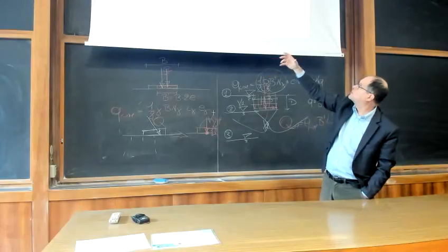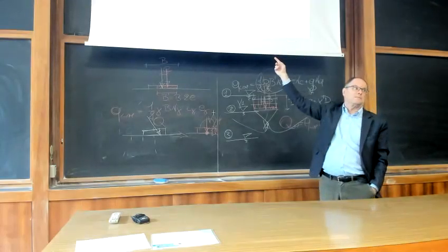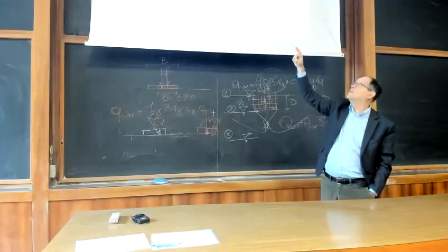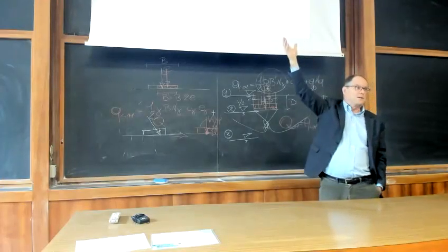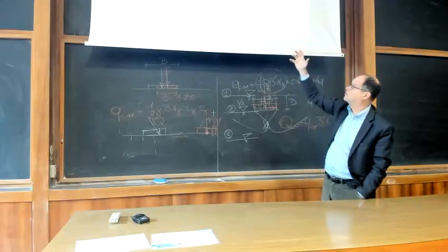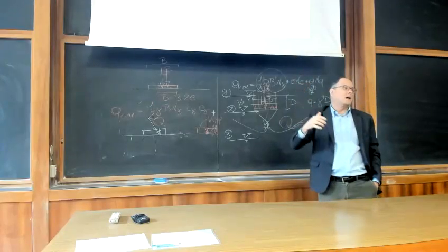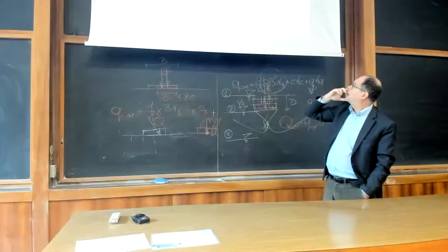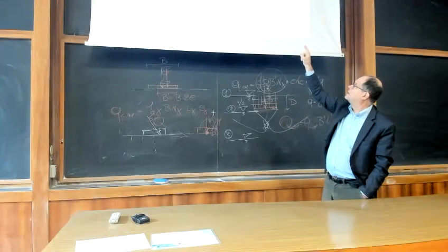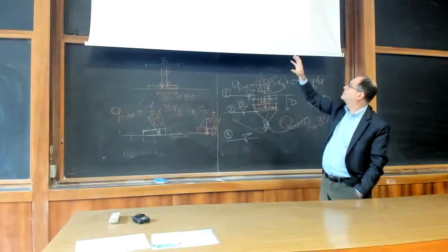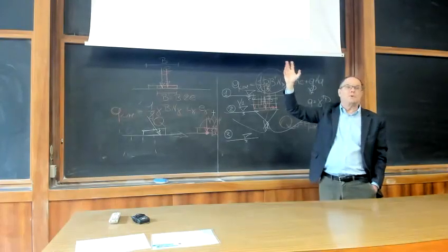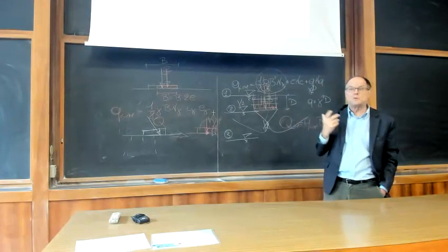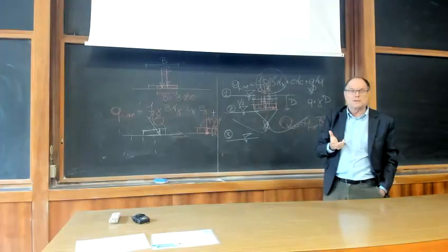A safe combination of H and V. If your load combination H and V lies outside the red curve, this means that you are unsafe. And you see, the red curve is not like the blue line. The blue line is in the assumption of no interaction, but the interaction between the two components is strong, is very important.